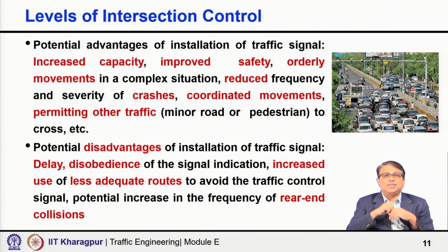One more important thing: we want to enhance safety, that is our very primary objective, but in some cases, due to installation of signals, rear end collisions may increase. So, if there are certain experiences of increased rear end collision, you have to rethink. I am not saying that removal of the signal is always the only solution, not at all, but such potential disadvantages one may also have to face.